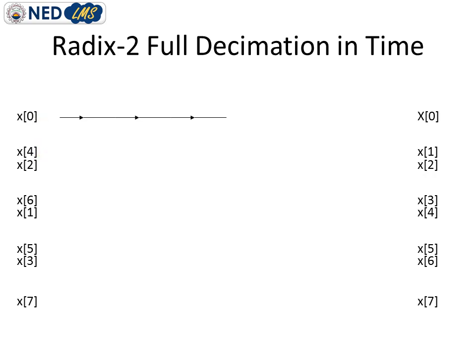We are actually going to calculate the frequency domain output. First of all, we have to draw straight lines. Then actually, as we are decimating the signal in time, we are taking 2 values DFT first, then after that 4 values DFT, then after that 8 values DFT.